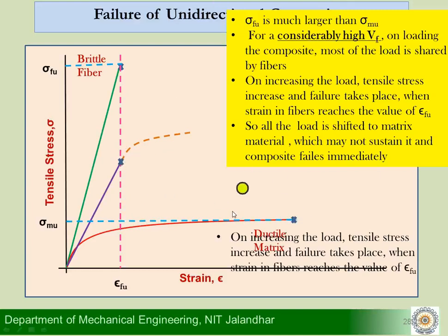And the composite failure will occur immediately. That's what I'm saying. The composite failure will occur immediately after this, the moment. So this happens when you have a high volume fraction. There will be considerably high volume fraction. And let me keep it pending, what is the meaning of considerably high volume fraction here.